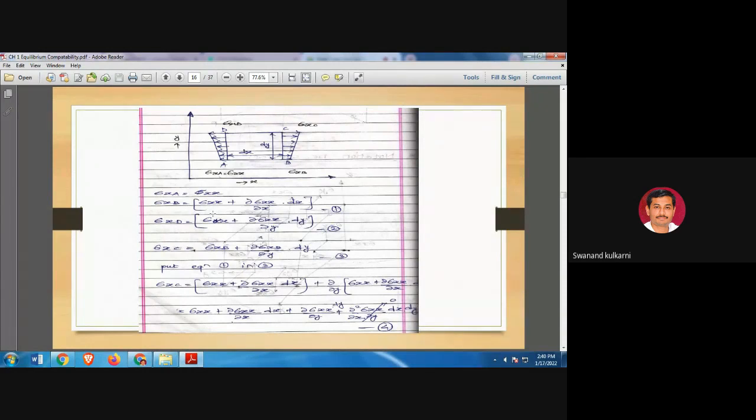Sigma xb is equal to sigma xx plus why we are adding this particular component here? Because our assumption is that due to location difference, due to uncertainties, or due to some undefined parameters, there may be this stress different at different locations.